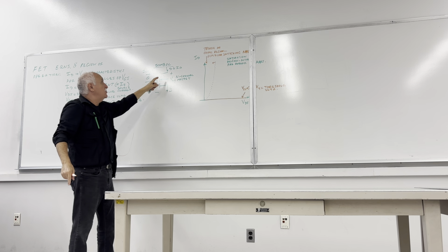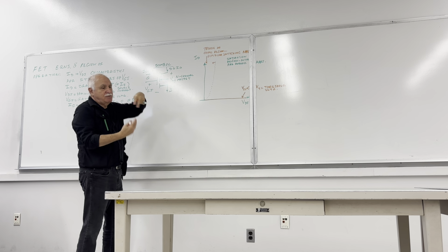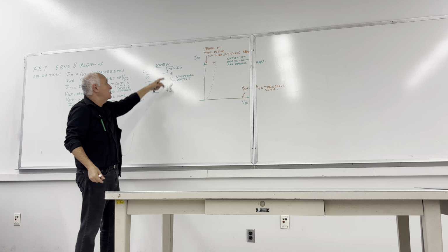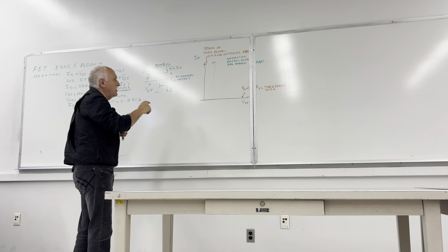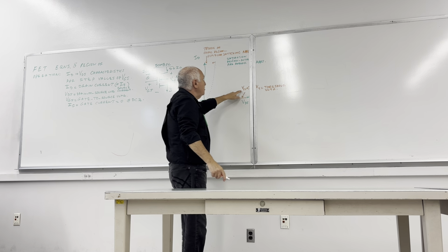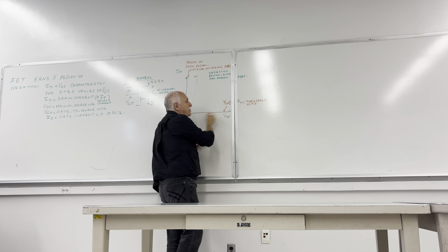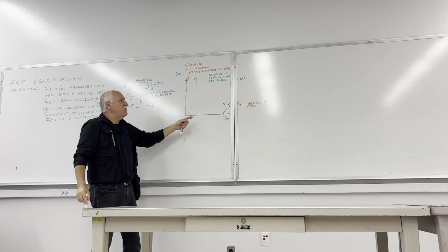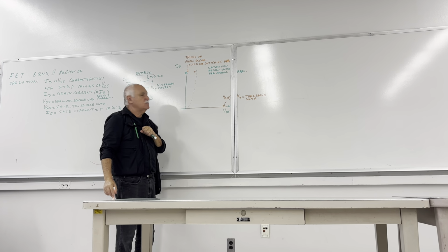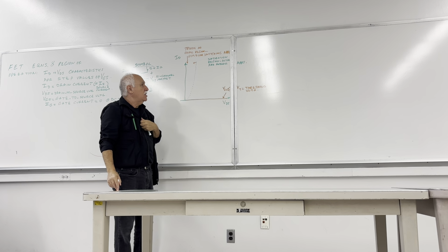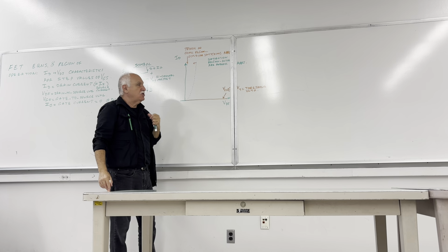Otherwise, between drain and the source, we have two diodes back to back, which are unable to conduct anything. With gate to source voltage equal to or less than VTH, there will be no current. You may have a voltage there, but if it is 0.1 of a volt, the transistor will not invert and enhance the electrons. Enhancement comes in when it exceeds a set threshold value.